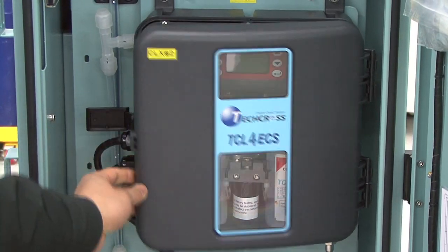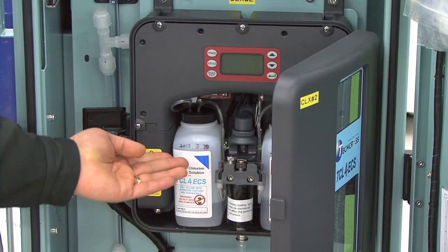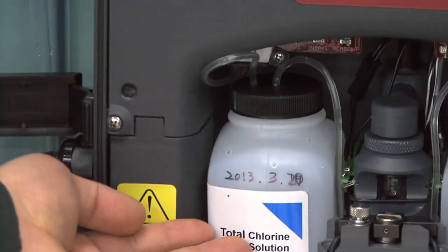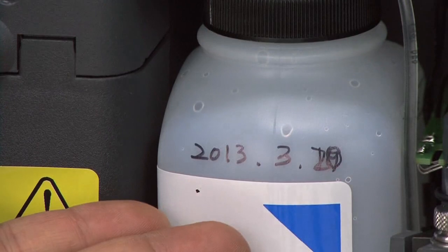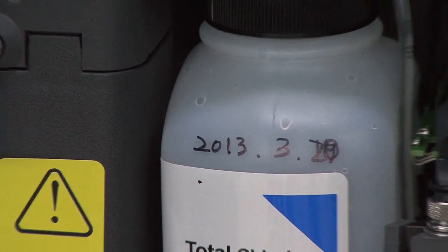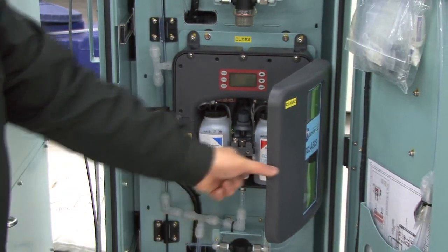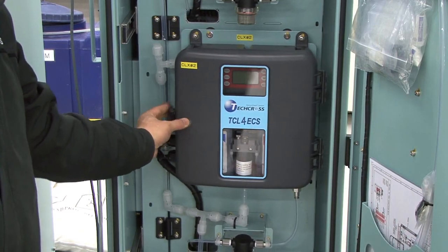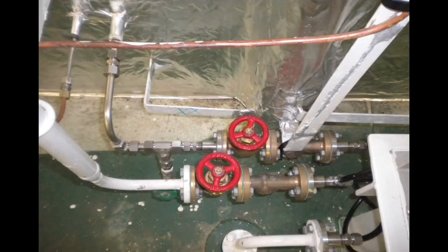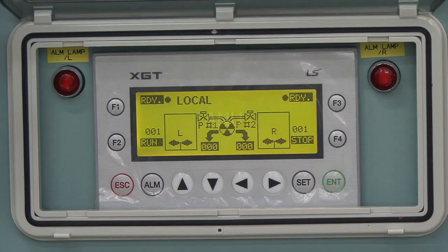2. Check replacement cycle and level of CLX before using. Left buffer, right indicator, replacement cycle every 2 months. Replace it with new one if it is expired. 4. Open or close each manual valve allotted to ballasting and deballasting.